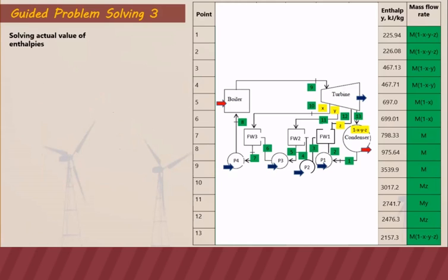The same also applies if we are given the isentropic efficiency of the pump: we will use the pump relationship for isentropic efficiency, which is the same that we discussed before for the actual cycle. You can go back to the topic to recall how to compute isentropic values. Using the isentropic efficiency of the turbine, which is 92% based on the problem.